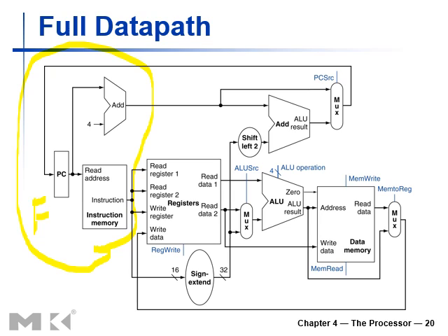Once the 32-bit machine code is extracted, the next thing is to get the operands in order to perform that specific operation. This register file will come in handy, or will be used in that particular operation. Then we've got the ALU to process the information. Then we've got the data memory for loads and stores, and then results are written back here.